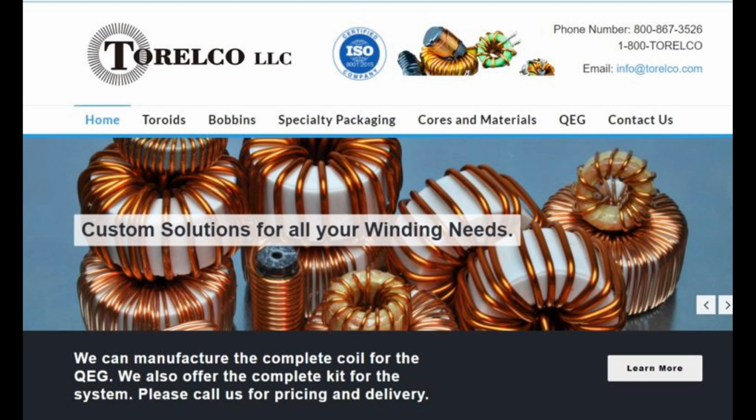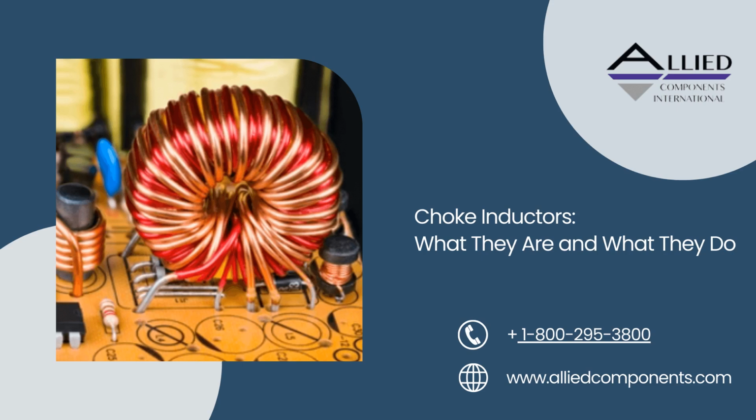Helps cold starts. A choke is crucial in starting an engine that operates on a carburetor, especially in cold temperatures. Simple mechanism. The design is simple and effective for controlling air-fuel mixtures without needing complex electronics. Disadvantages. Fuel inefficiency. When the choke is on, the engine consumes more fuel, reducing fuel efficiency.